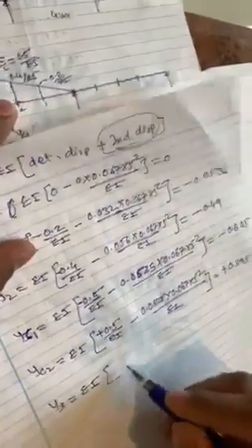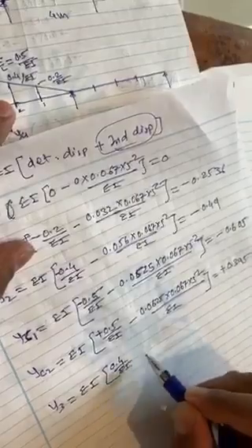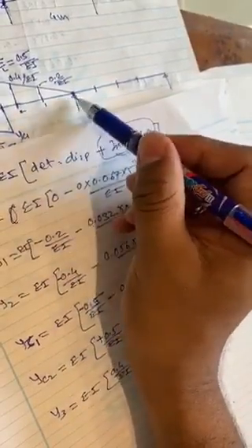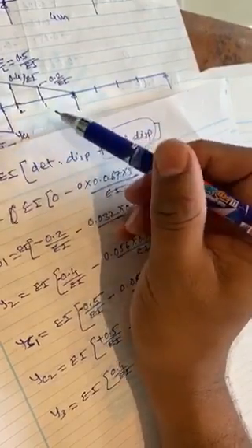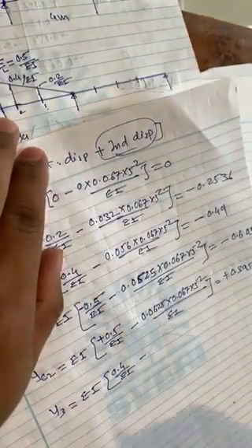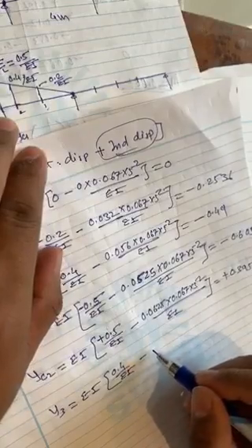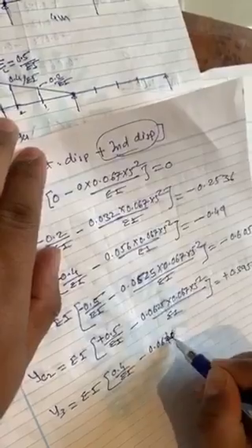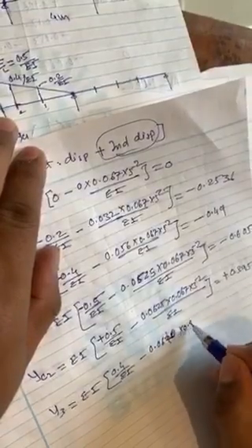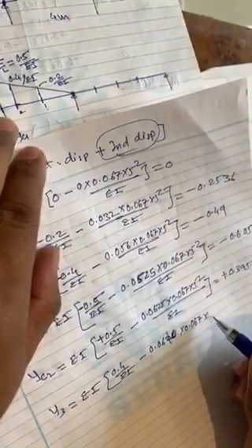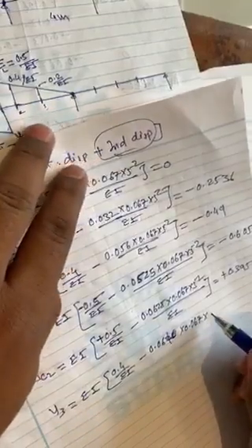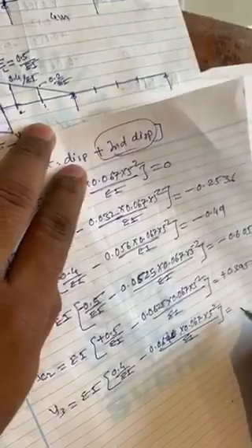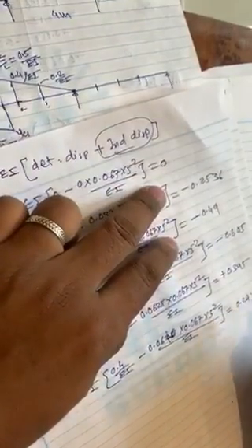Now we'll go to this point, that is 0.4 by EI, so we will call it y3. EI into bracket 0.4 by EI minus, from this side it has now become n as 0.6. For n equal to 0.6, the value of k will come out as minus 0.064 into 0.067 into 5 square, and we have to be very careful with the span here, divided by EI, and this comes out to be 0.292.